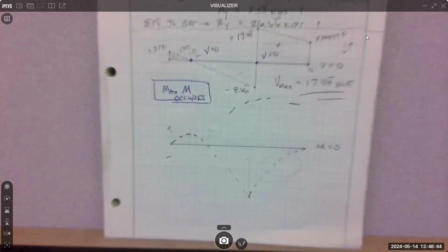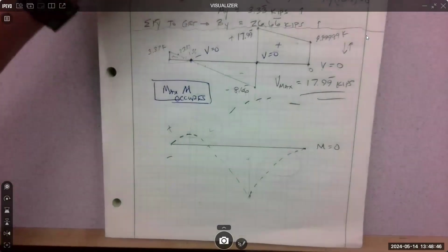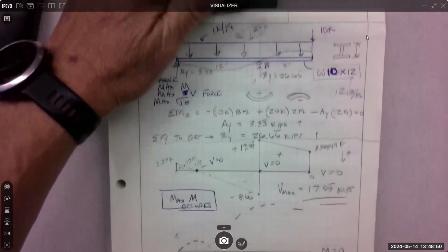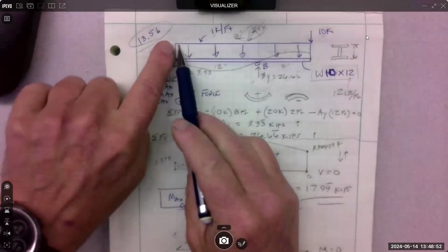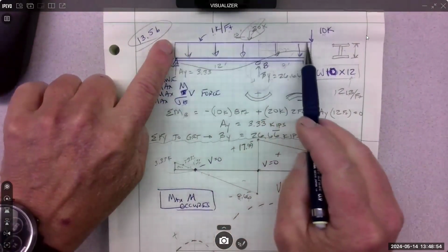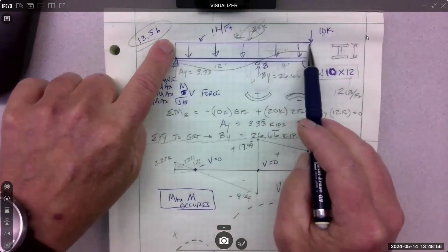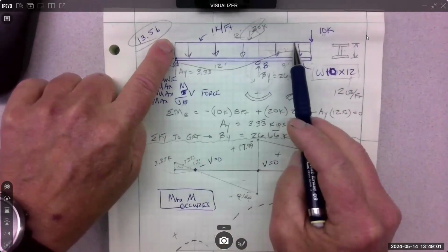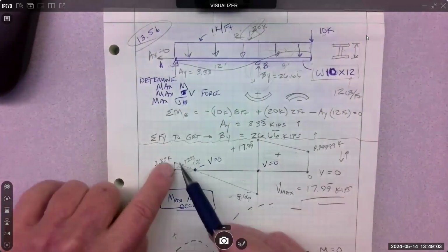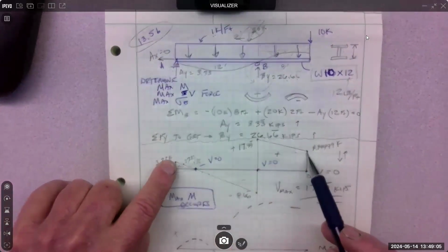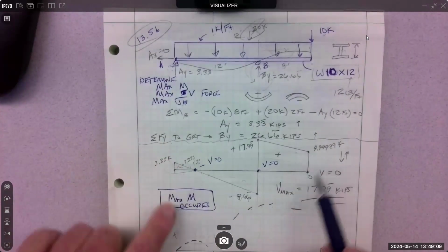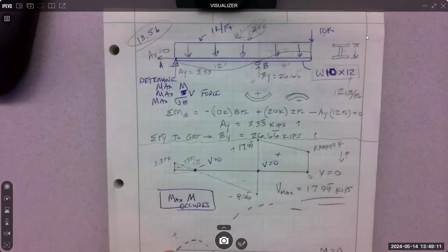So for you wondering about the derivative, some of you won't like this, but some of you will. Uniform in this is called the load curve. This horizontal load curve creates a slope, linear, in the shear diagram, which creates a second degree parabola in the moment diagram.